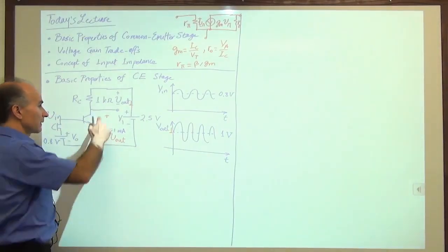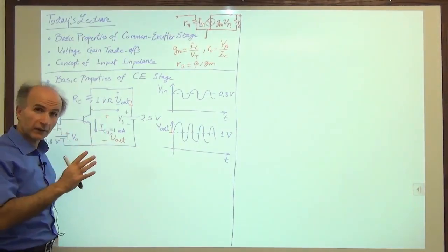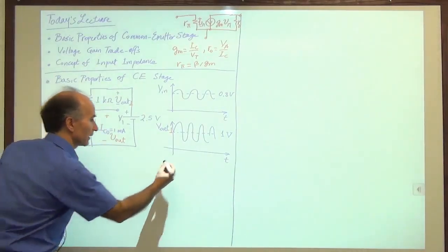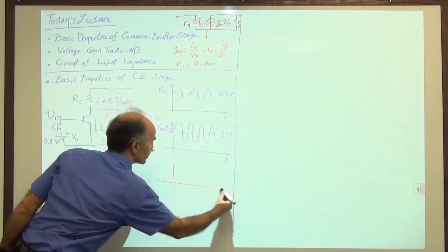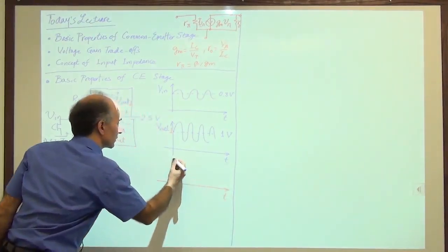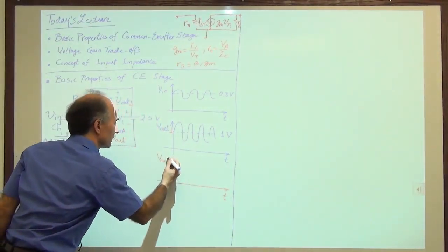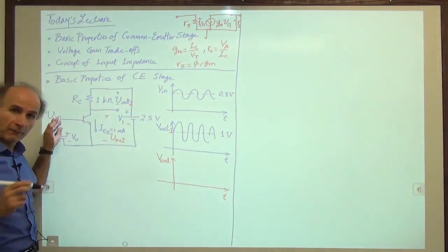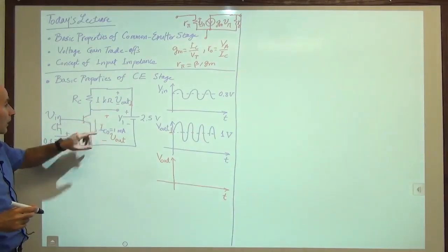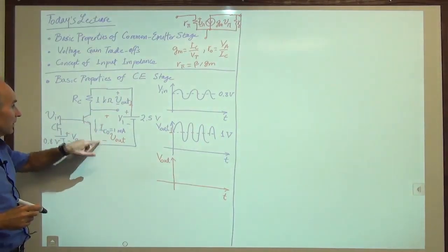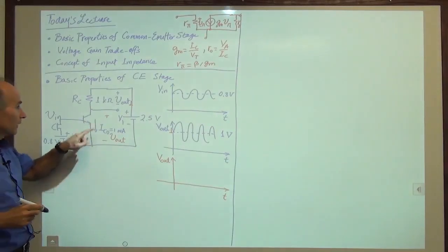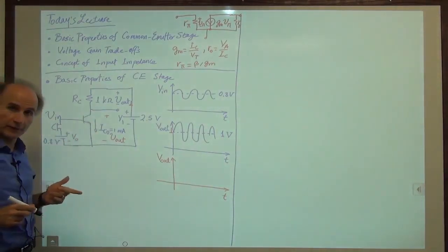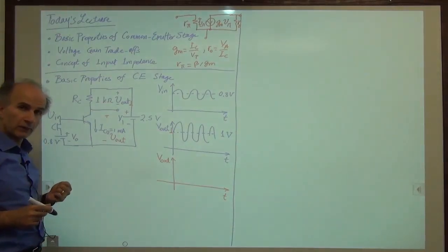So again, let's plot this voltage, including everything, DC, AC, etc., to see what it looks like. So here's that V out. Again, no signal. If you have no signal, what happens here? Well, we have 1 milliamp of current coming down through this resistor. How do I find this voltage? This voltage happens to be the collector emitter voltage, right? Okay, how do I find that voltage?